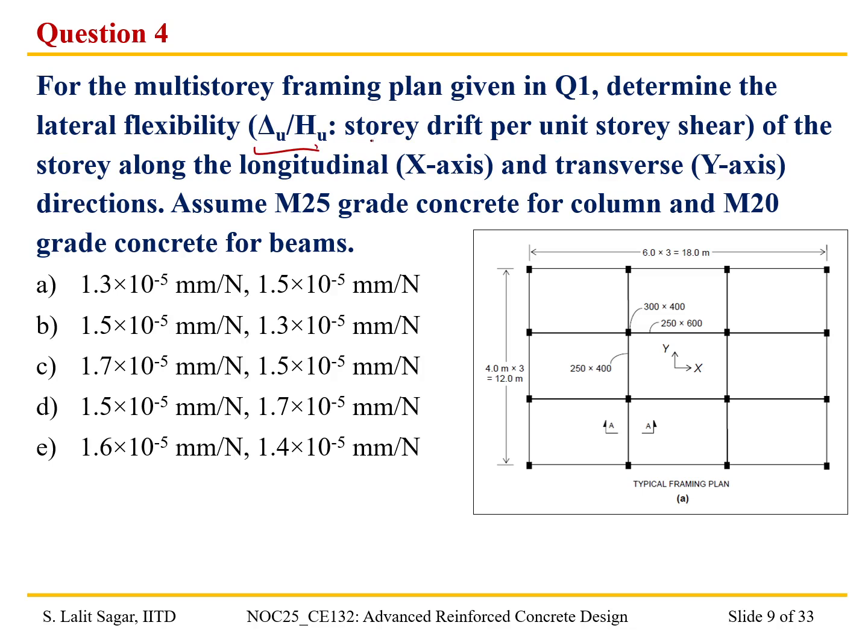We need to determine the value of delta u by hu, which is called the lateral flexibility or the story drift per unit story shear of the story along the longitudinal and the transverse directions.